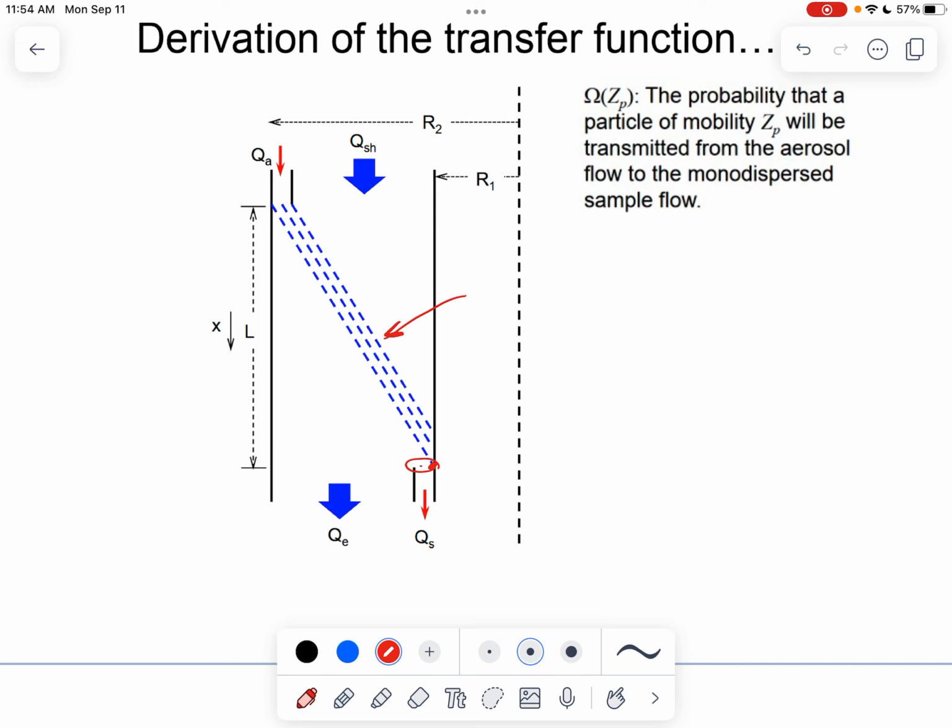So you can see that there will be scenarios where the smaller particles will also follow a certain trajectory and then get collected through the aerosol outlet. So we're talking about aerosols with sizes, let's say, between this range, that can follow trajectories between this range. So a little bit smaller particles can still go through, right? They can still enter this aerosol outlet, right? And then when the particles are further smaller, let's say their trajectory goes along this way, then they will not get collected anymore. They will just get collected onto the center electrode and stay right there, right?